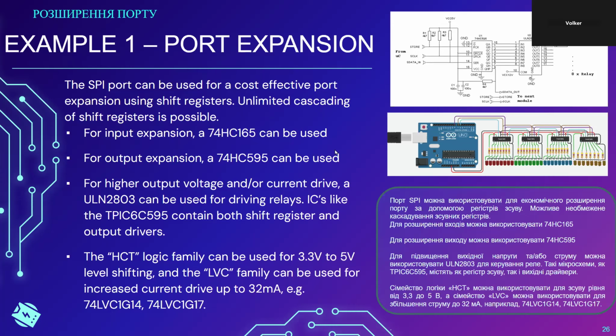Basically there are different types of drivers that you can attach to a microcontroller output. You can also connect a MOSFET directly to a microcontroller output. Depending on the current that you need and the way you want to connect that motor, a typical on-off method is to use a low side driver.